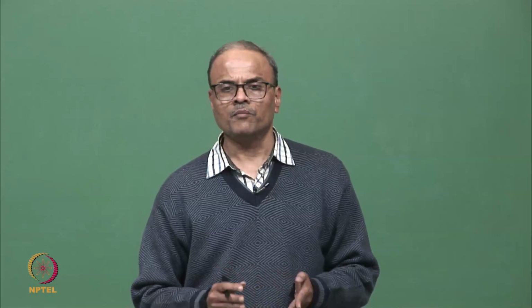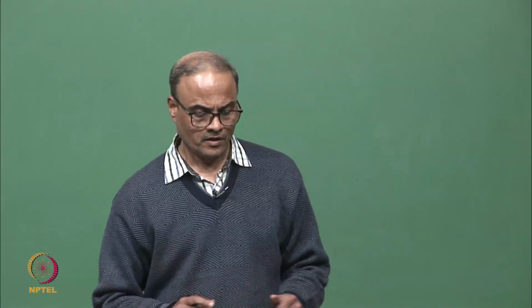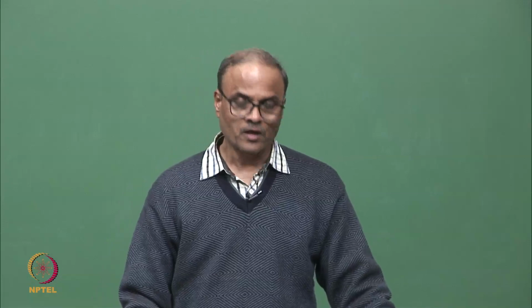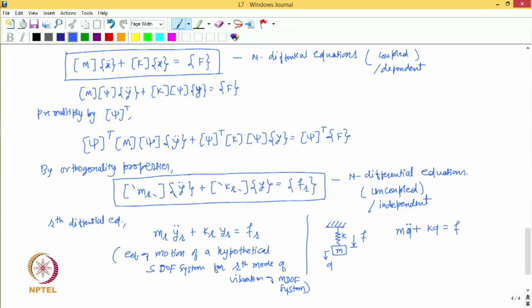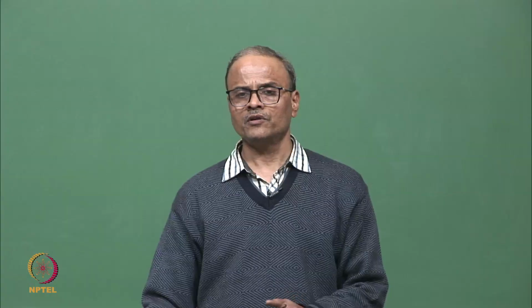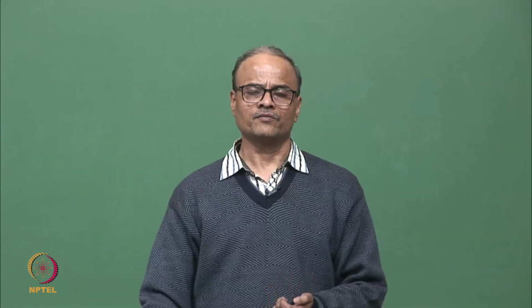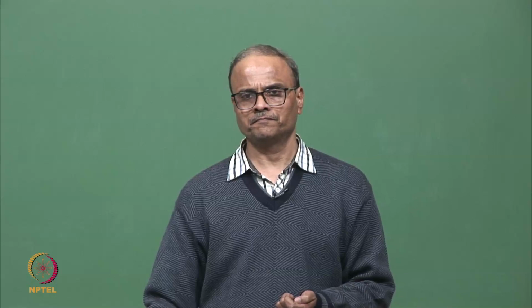And because we can look upon this as a hypothetical single degree of freedom system whose mass is mr and kr is the stiffness, and because this equation corresponds to a mode of vibration, we refer to these quantities as modal mass and modal stiffness.